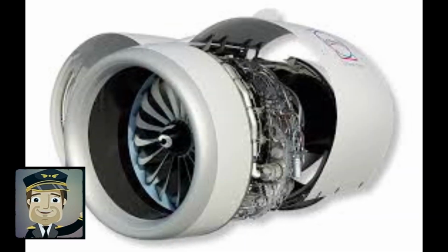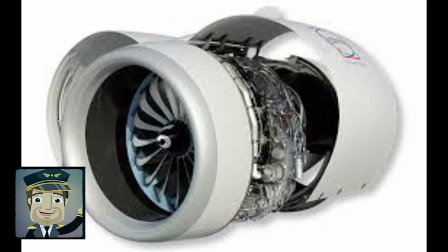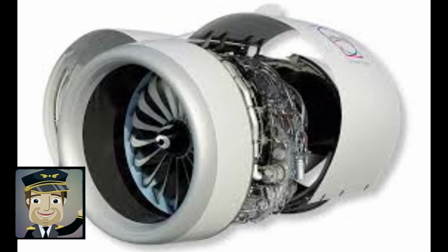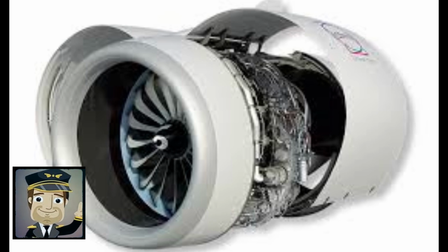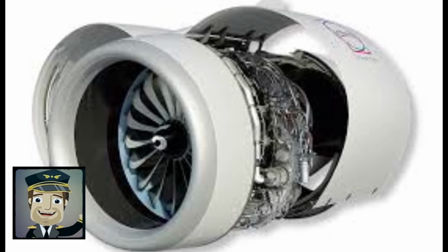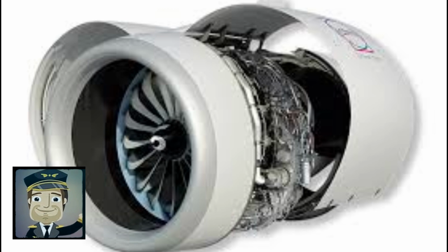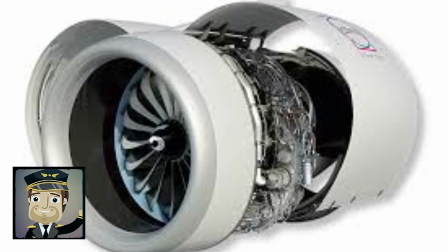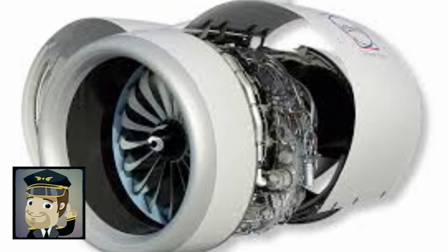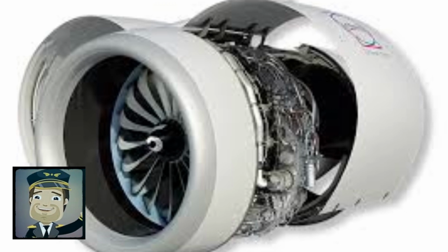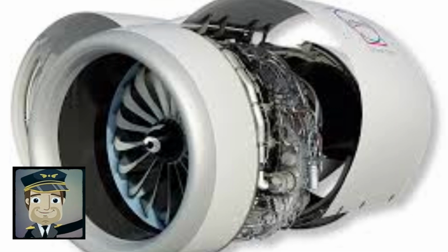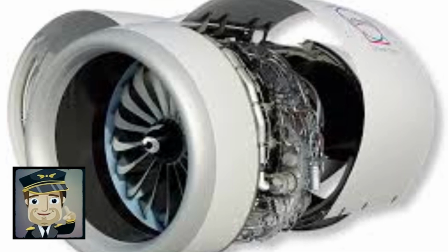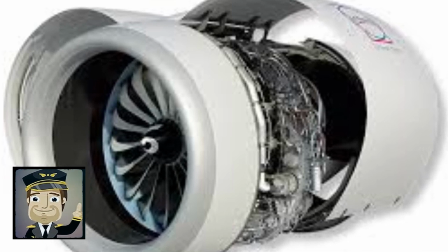Rotating and static ceramic matrix composite parts operate 500 degrees hotter than metal and are 1/3 its weight. GE is investing $200 million in the ceramic matrix composite, which will be used 10 times more by the mid-2020s. Rolls-Royce aimed for a 60-to-1 pressure ratio core for the 2020s UltraFan and began ground tests of its 100,000 horsepower gear for 100,000 lbf and 15-to-1 bypass ratios.